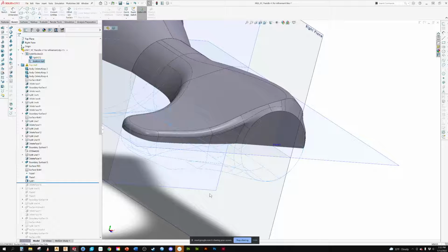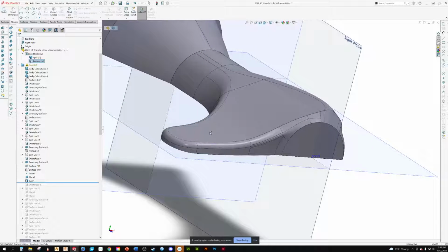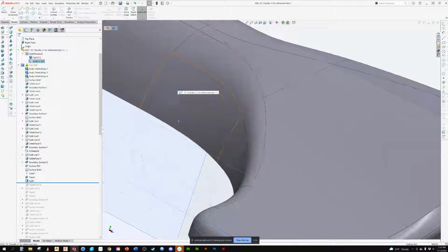So this is where we come back with a plan of attack. You know, looking at this and saying, okay, the problem is that at this point, the curve is not draftable. So what am I going to do? I'm going to start deleting faces, putting faces back in, using splines to control the surface.